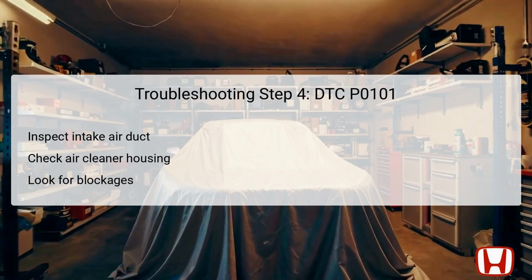The fourth troubleshooting step for the DTC P0101 requires a detailed inspection of the intake air duct and the air cleaner housing. The aim is to identify any blockages, restrictions, or damage that could interfere with airflow to the MAF sensor. Start by inspecting the intake air duct for faults like cracks, leaks, or obstructions that could disrupt the airflow dynamics, which is crucial for accurate MAF readings.